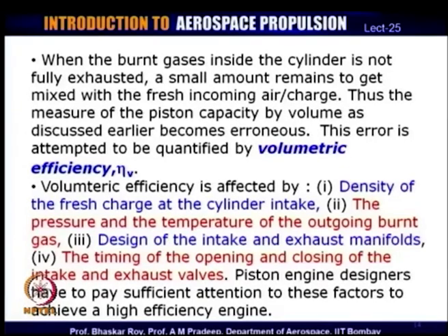Okay. So, the closing of the exhaust and the timing of the exhaust and the intake manifolds is of great importance, and this is where the mechanical engineering comes in a big way. So, the engine needs to be designed to create very efficient intake and exhaust manifolds, otherwise it will affect the volumetric efficiency and the timing of the opening and closing of these valves.